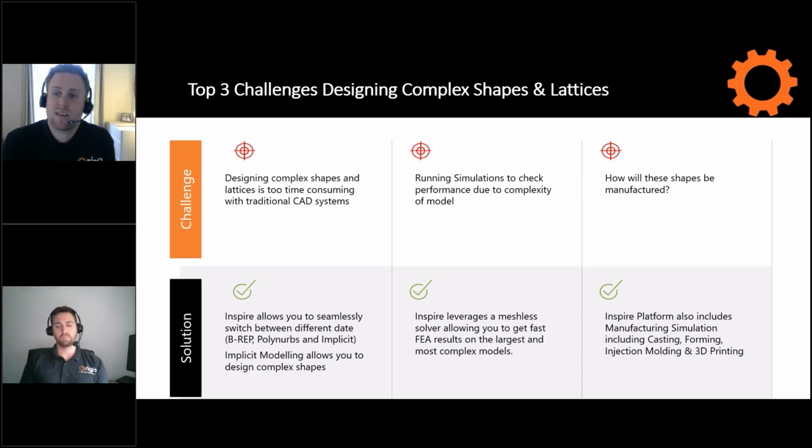One of the reasons this is a challenge is because traditional CAD systems utilize what we call BREP data. In other words, curves and faces where there are quite defined boundary conditions. So when you are doing operations like shelling or offsetting geometry, it often tends to clash, which can cause problems.